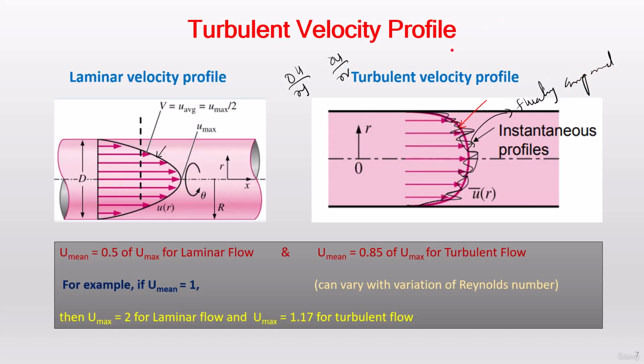Okay. So now I can put my u as a function of t, that is the instantaneous velocity profile, equal to the u bar, u average, and the u dash. So this is the average velocity over here, and any change that we are modeling from the mean velocity is the u bar, and that definitely is not a constant value. But when we solve the problem using the RANS or the eddy viscosity models that we usually use for CFD, like k-epsilon, k-omega, these models assume that this change is constant.